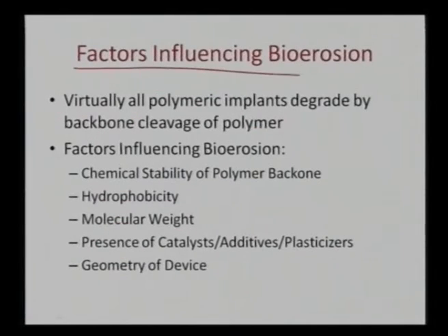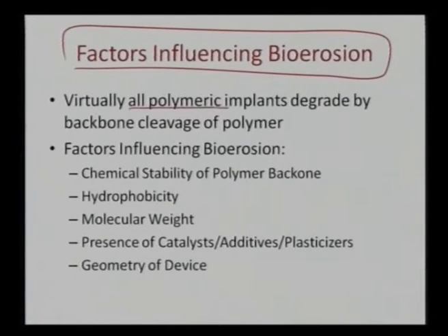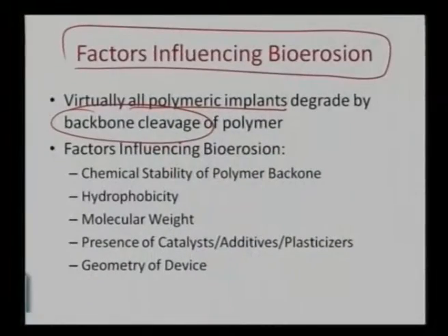Again, regarding the factors which influence bioerosion: virtually all polymeric implants which degrade do so by backbone cleavage. As I said earlier, backbone cleavage is the eventual consequence of all the processes, because that is what results in the degradation of a polymer into water soluble components. Apart from that, there are certain factors which can influence the bioerosion, and one is the chemical stability of the polymer backbone itself. If the backbone is much more stable, it will not allow easy degradation of the polymer.